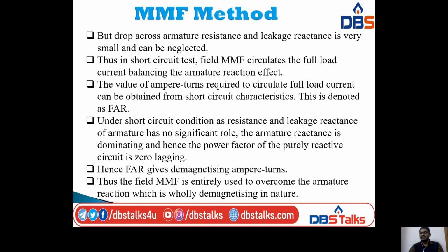Under short circuit condition, the resistance and leakage reactance of the armature have no significant role, because the drop across the armature resistance and leakage reactance is very small, that's why I am neglecting those drops. The armature reactance is dominating, and hence the power factor of the purely reactive circuit is zero lagging.